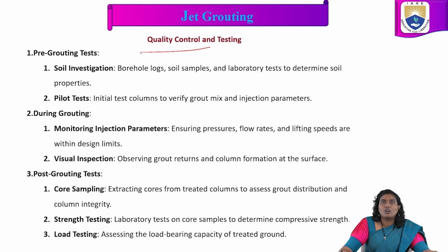During grouting: monitoring injection parameters and visual inspection. In monitoring injection parameters, ensuring pressures, flow rates and lifting speeds are within the design limits. In visual inspection, observing grout returns and column formation at the surface.